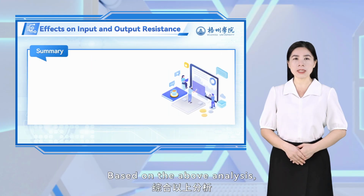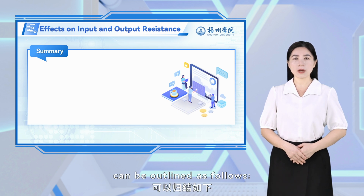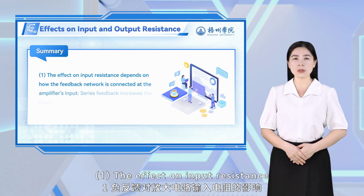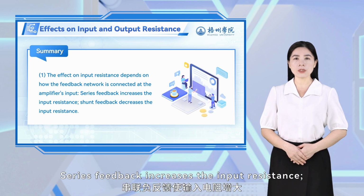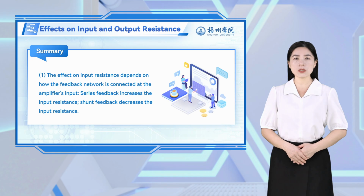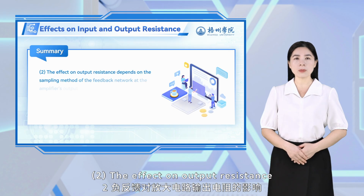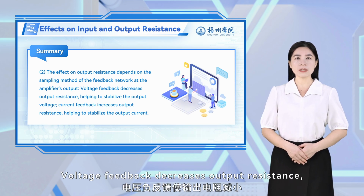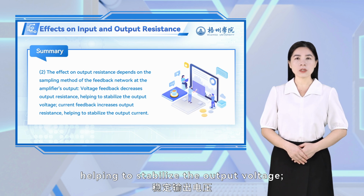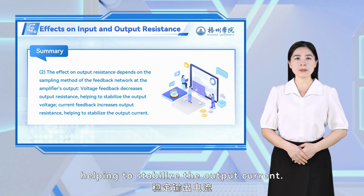Based on the above analysis, the effects of negative feedback on an amplifier's input and output resistance can be outlined as follows. 1. The effect on input resistance depends on how the feedback network is connected at the amplifier's input. Series feedback increases the input resistance. Shunt feedback decreases the input resistance. 2. The effect on output resistance depends on the sampling method of the feedback network at the amplifier's output. Voltage feedback decreases output resistance, helping to stabilize the output voltage. Current feedback increases output resistance, helping to stabilize the output current.